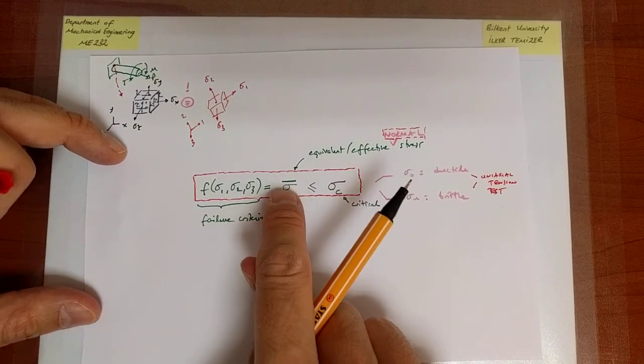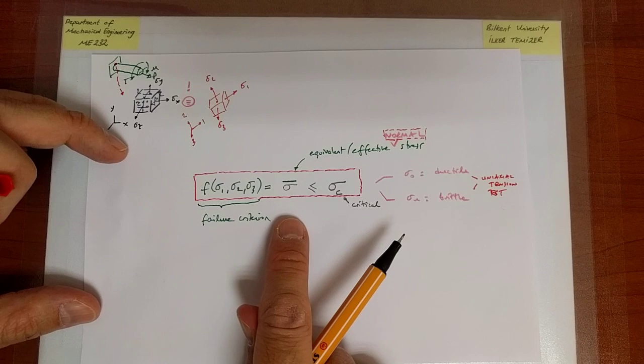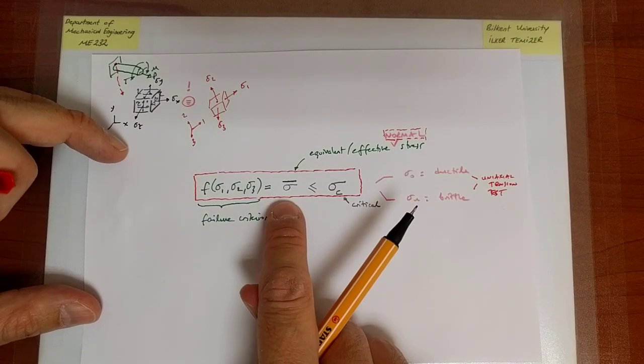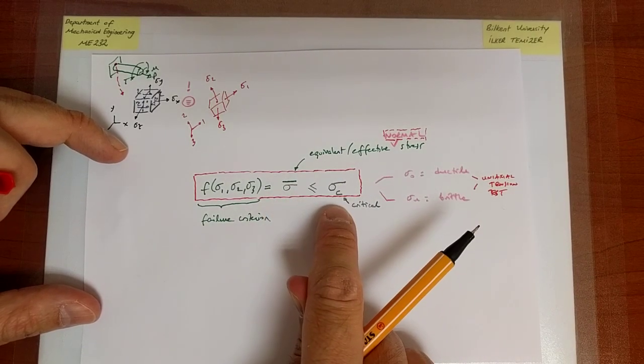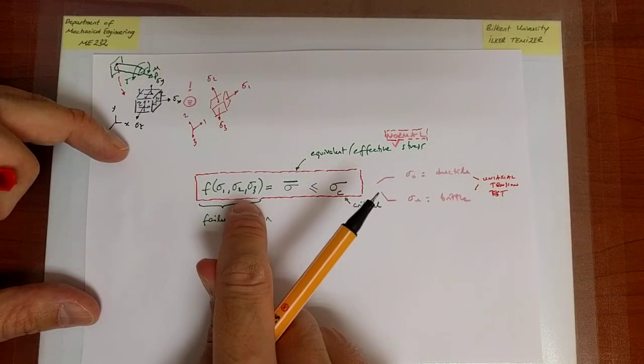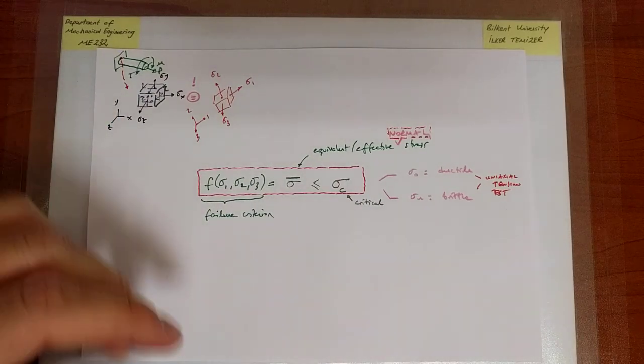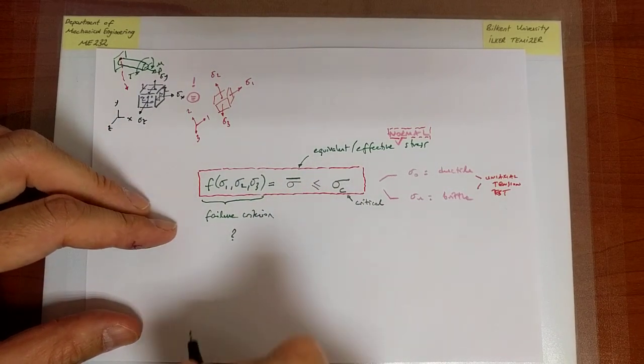Okay, so in other words, when sigma bar is simply sigma y, let's say in the very first example that we gave in the previous slide, the largest value sigma y can be is, in the previous example, sigma naught. Simple, right? But if there are multiple stresses present, then what is this criterion is now our leading question. How shall I formulate it?